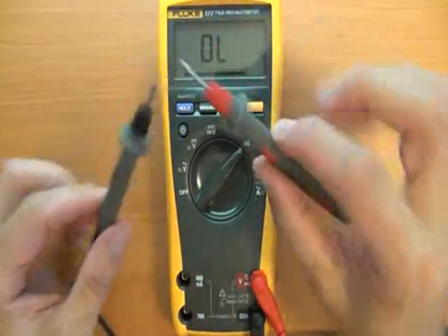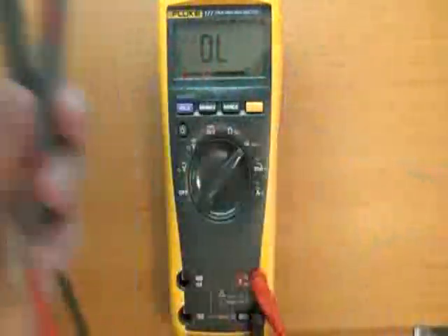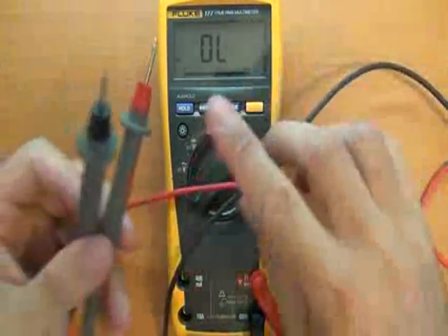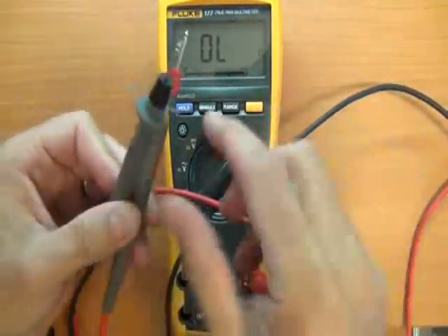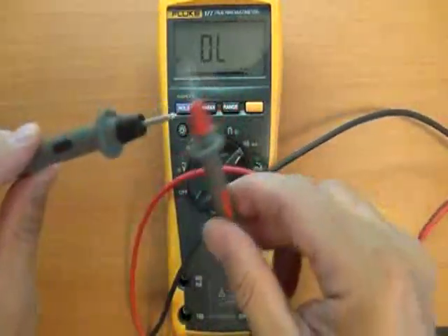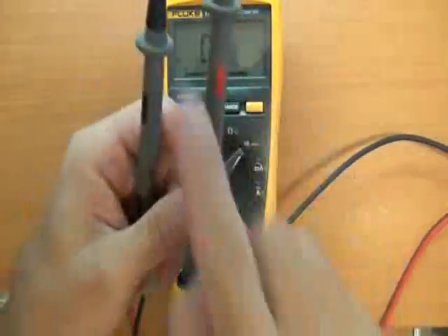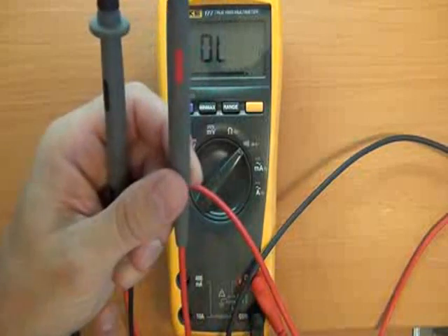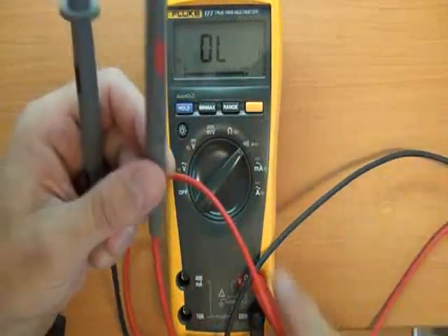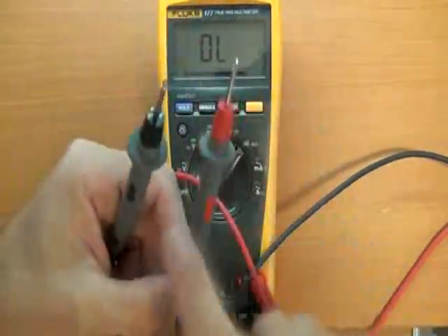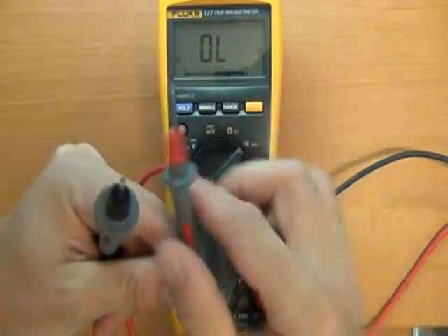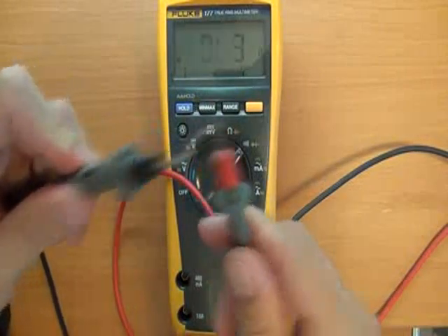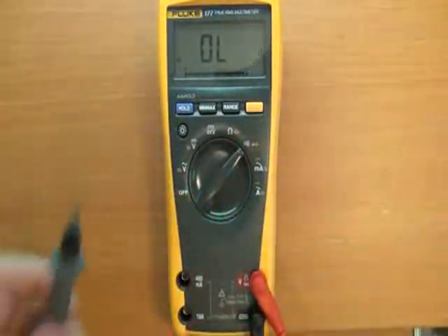Right, so we've got it there, and as you can see, the reason we're getting that buzz, which means we're getting a complete flow from end to end between two points, is because of our test leads. It's sending a test current and voltage through the wire to the multimeter to see that it's got a continuous flow between this point and through the multimeter. And if we put them together, we get that beeping sound.